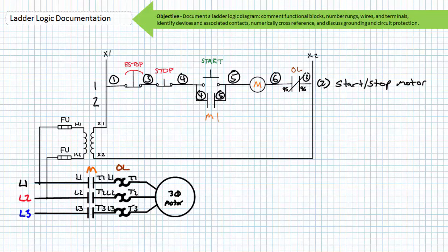Note that when rung 1 is energized, something in rung 2 closes. The normally closed manual buttons would receive terminals 1, 2. The normally open push buttons would receive terminal numbers 3, 4. The auxiliary M1 contact, being normally open in nature, would receive terminals 1, 3, 1, 4, and the M coil would have terminals A1, A2.